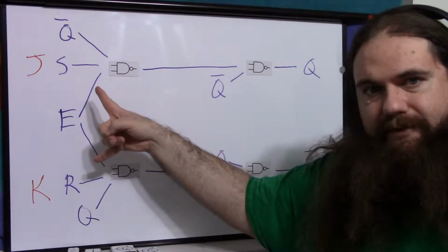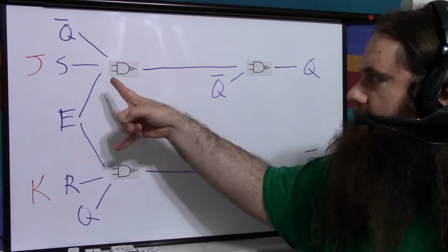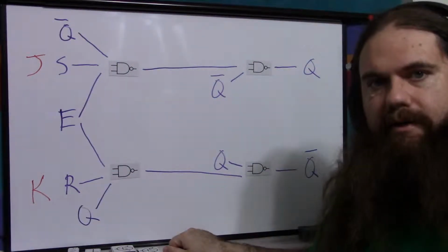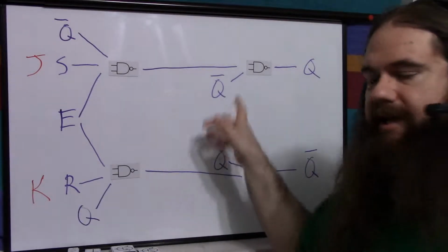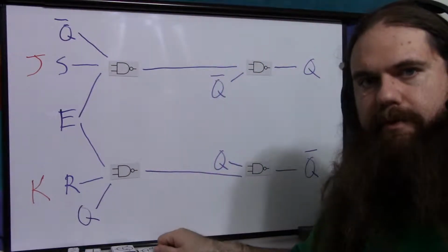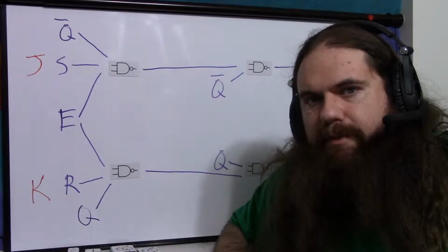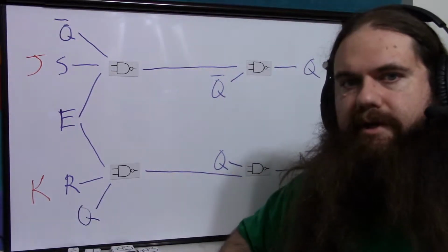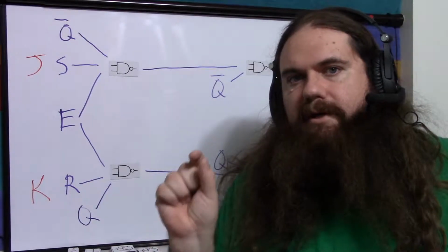So now, you've got set and reset over here, you've got Q and not Q both 1, and now you start pumping a 1 to both, and you're in your invalid state, and everything's going back and forth, and it's super goofy. There's 2 ways to solve this problem. One way is to use something called edge triggering to create not just a clock signal, but a clock pulse.